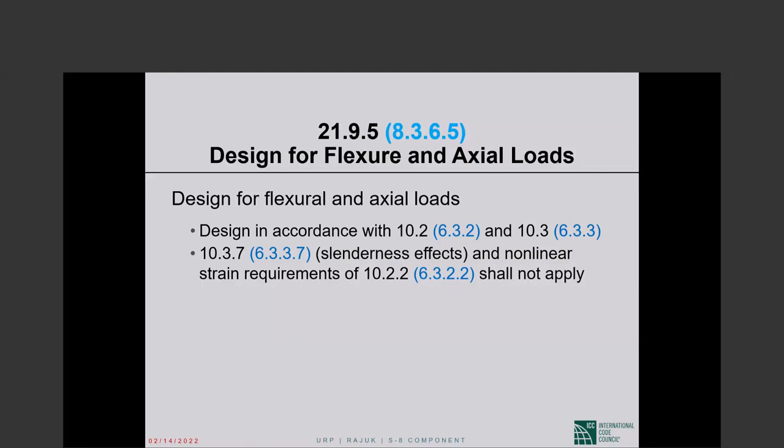The infill actually used to get damaged in an earthquake. There was diagonal shear cracking leading to the failure of the infill, and the frame ended up doing the seismic resisting. But those days are long behind us. Shear walls, for a long, long time, have been monolithic concrete construction. The columns at the end and the web are constructed at the same time.